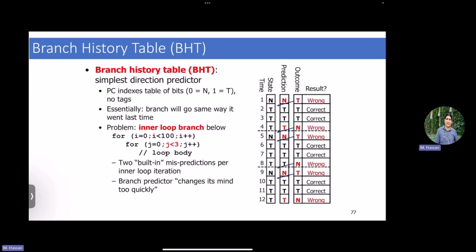Also in lab 2, you experimented with the tables, whether it's the BTB or the G-share branch predictor. So how do we really keep history? How, through the table, are we able to predict whether the coming branch is taken or not taken? Taken means I jump to the branch target, not taken means I don't jump and I execute the subsequent one. So assume I have an example like this.